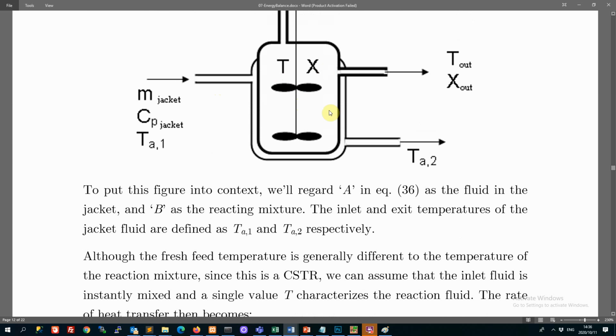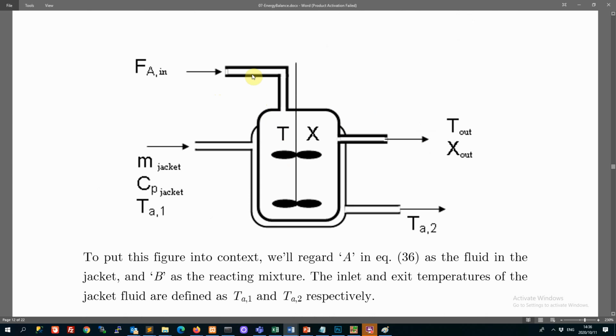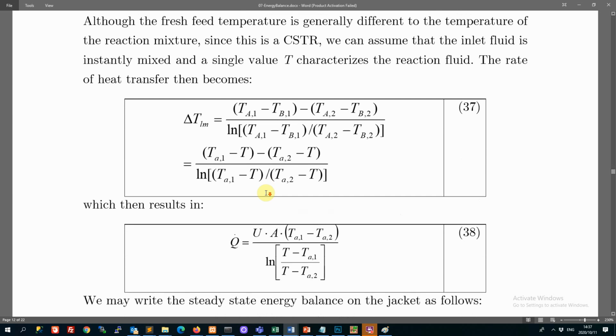And this is not quite a double pipe because you've got, number one, flow in this weird way here, coming in here and going out the side there, and then you've got flow in at one point and across the jacket and out at another point. So it's not quite the same as the double pipe flow. Here there's no flow straight through. It's not like the flow is straight down here and then straight around there. It's a little bit different.